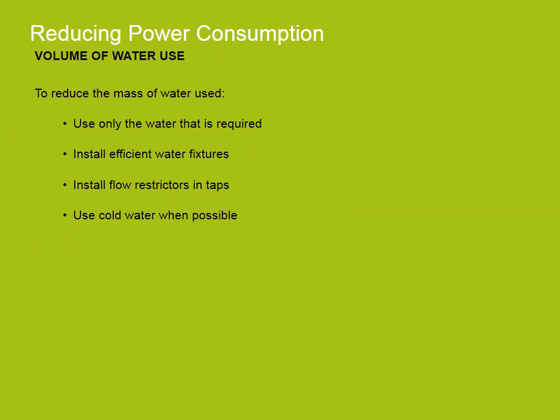To reduce the amount of water used or heated, some recommendations you can make to your clients include: use only the water that is required to do the job, install efficient water fixtures, install flow rate restrictors in taps, and use cold water or cold washing when possible.